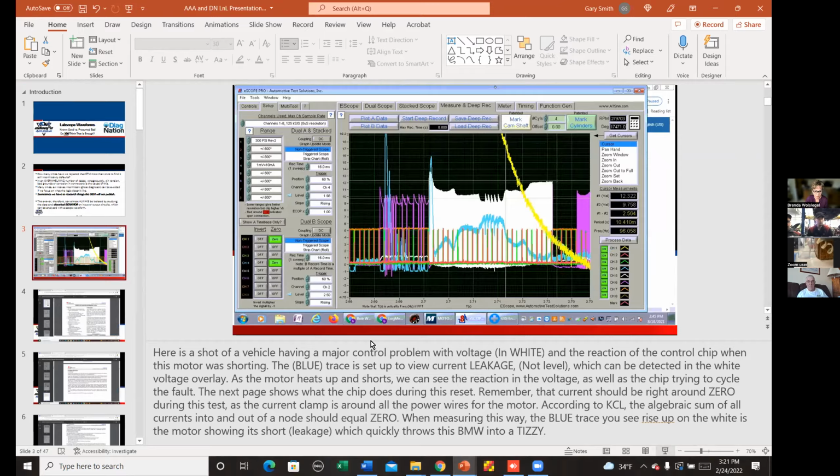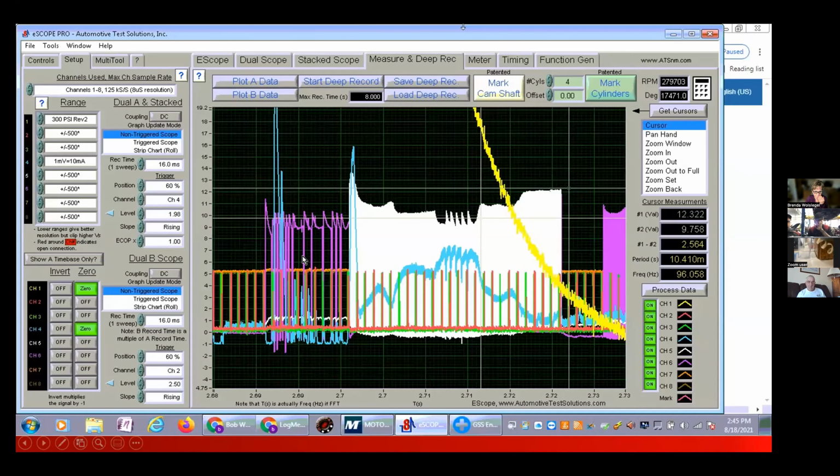it's at the point where these phases change and the next phase turns on that we're getting leakage from the shorted winding onto the other two windings. And this pattern repeated itself. Notice that as the inductive phase energy drops, so does the short. See that, guys?